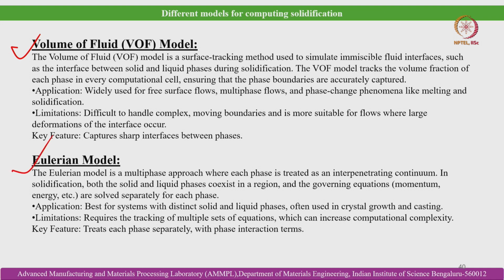The Eulerian model is a multi-phase approach where each phase is treated as an interpenetrating continuum. In solidification, both the solid and liquid phases coexist in a region, and the governing equations such as momentum, mass, energy, etc., are solved separately for each phase. Not only the solid and liquid.